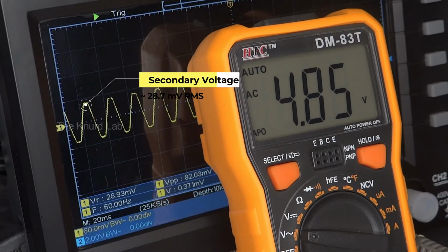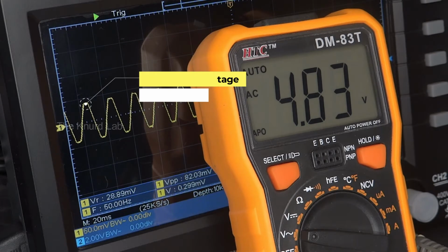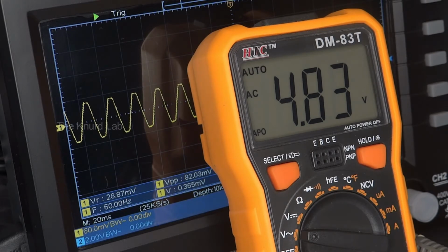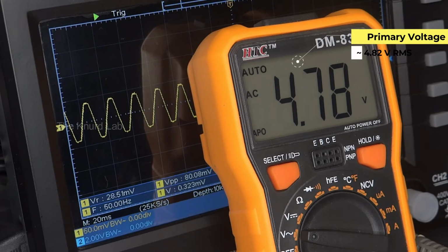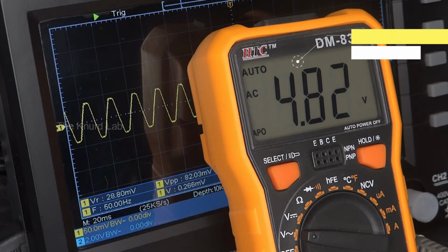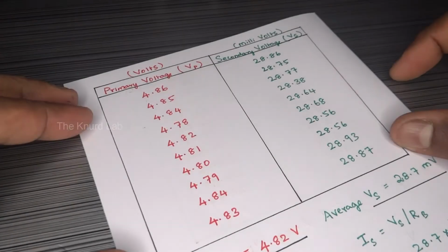The tolerance of the resistors, the accuracy of the multimeter, and the delay in observing and recording the primary and secondary voltage at the exact moment which they change could all introduce a certain degree of error in the calculated value.